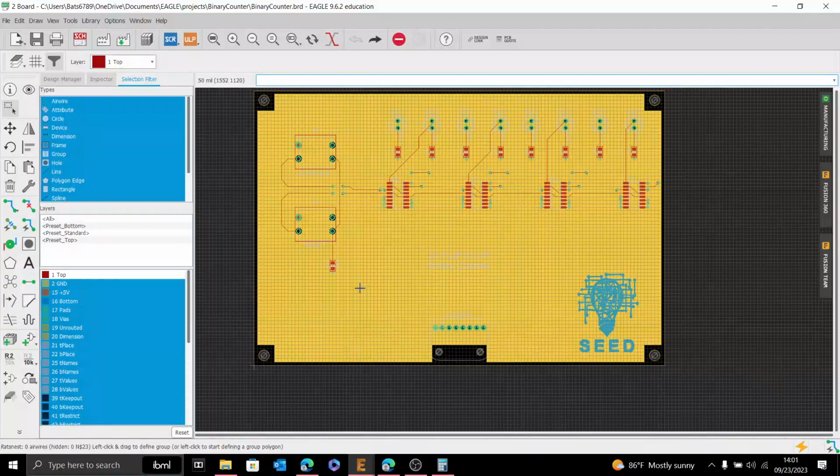A couple of ideas with a 4-layer board is that you either put both of these in the middle and all your traces are on top, or you have all your traces in the middle and 2 ground planes top and bottom. I did top and bottom traces so that you could see the traces, and then 2 internal power and ground planes.